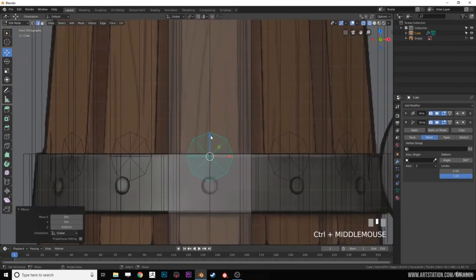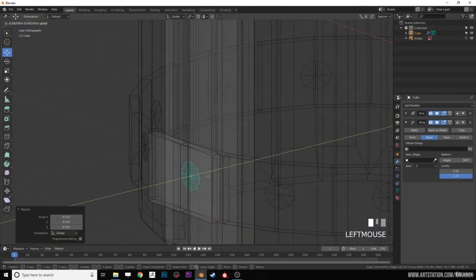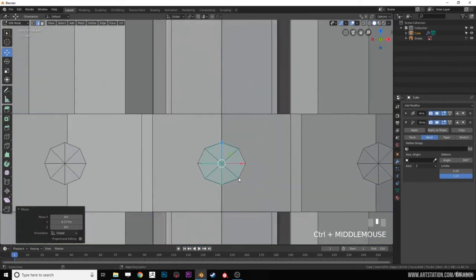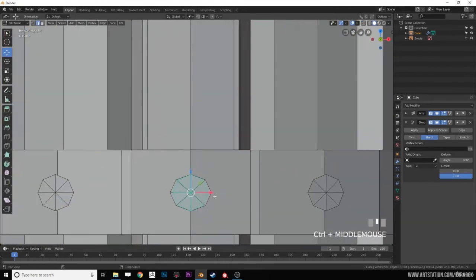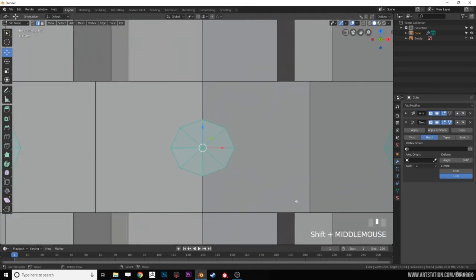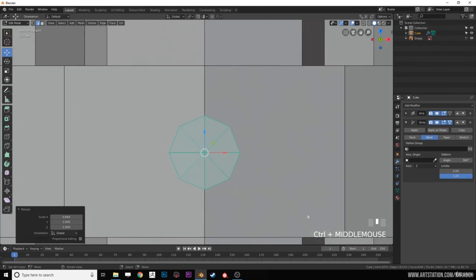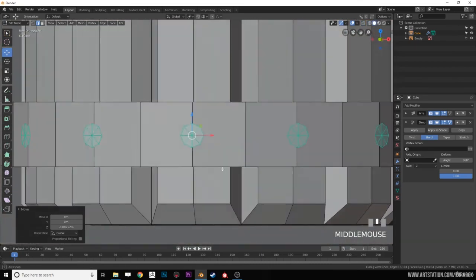Okay, I'm going to move this down right here and I'm going to scale it and move it a little out. And here, as you can see, there is a stretching in the sides, so we need to scale it on the x-axis. To correct that, go here to activate the vertex and we're going to scale it in the x-axis. Press S and X and move it in such a way that it reaches the circular shape. I'm going to scale it another little bit, and here in the reference it has this size, but I want it a little bigger.